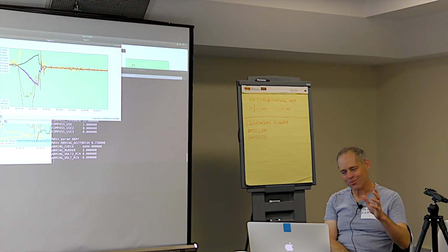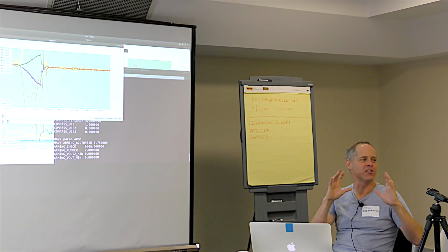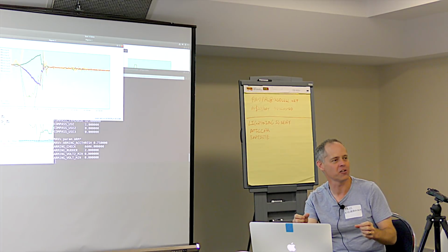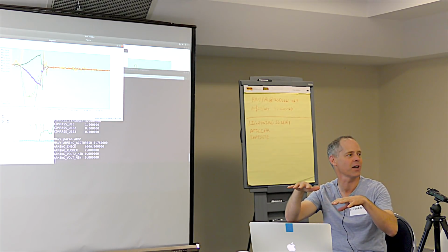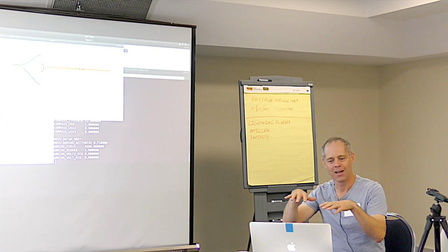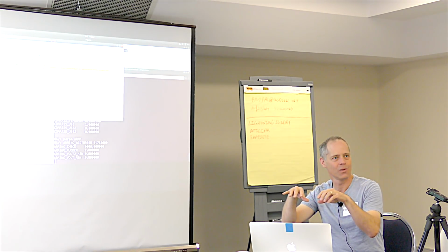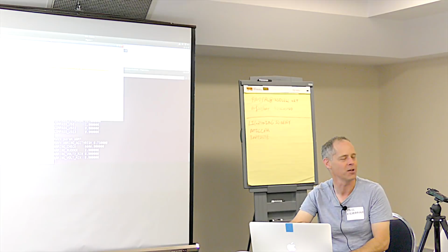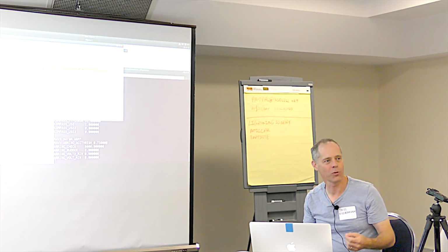Now, this is what happened with this sequence of events. The copter takes off with absolutely ridiculous levels of magnetometer interference. It's failing. EKF1, the first instance of EKF, fails, then the second instance, EKF2, fails. They're failing alternately depending on what orientation the copter's at, and because it tended to hover at this point in time. At some point, the IMU1 EKF fails. The IMU2 EKF is momentarily healthy. It switches to the IMU2 EKF, which has got the rotated IMU, and then the copter immediately just flips onto its back. And that was the failure mode. So it was more than one thing.